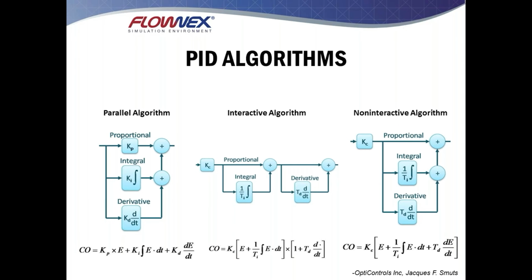The digital control is typically high-level control at the DCS level, where basically decisions are made inside of the control system. This is adjusting ramp rates based on transfer functions, or turning on or turning off systems based on load requirements. It's very much logic structured, Boolean control, if you would call it that. And the other type of control is analog control. This is your PIDs, processes or controllers that receive an analog signal. Based on that, compute a control output. And these controllers themselves need to be tuned.